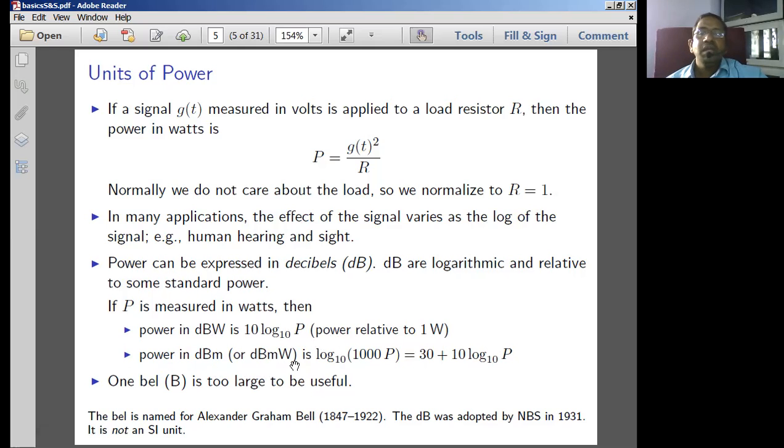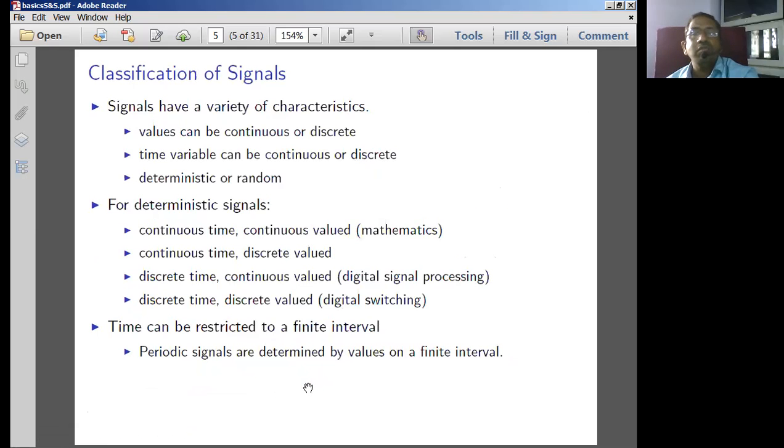If the signal value is going to be more than 1 watt, then we can represent by using dBW type of the scale. So if at all we represent power in decibels, then we simply perform 10 log of that particular value of the signal. So that means this decibel unit is normally used for too large values and too small values of the power signals.